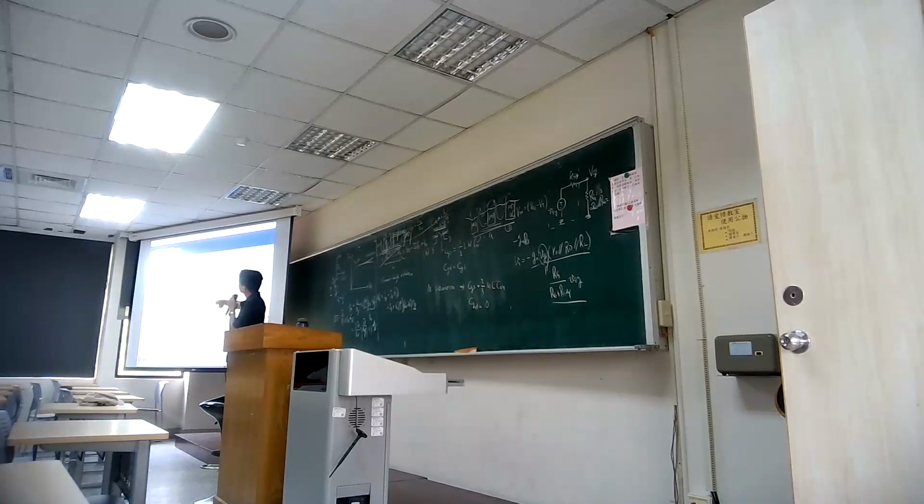So you can use the Miller effect to treat it like a blank box. If you have a system with two different voltages with a certain coefficient, you can use this way to separate the connection. For instance, if your V2 over V1 is a function of K, then you can divide this component into input and output parts with equivalent impedance. This impedance is replaced by Z over 1 minus K, and then Z over 1 minus 1 over K. So you get a new impedance on both the input and output side.